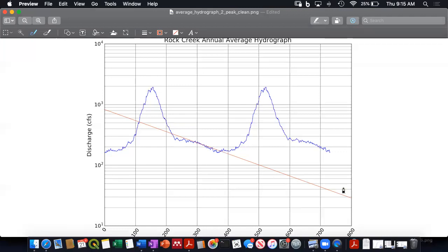All right. So I fit this line, and I extend it. Now, I want to know the number of days it takes this line to go over one log cycle. So the trick here is just to pick a couple spots where the line crosses intersections. So for example, right here at 100 days, here's 200, 300, 400, 550, right? So at 100 days, I'm at 550.